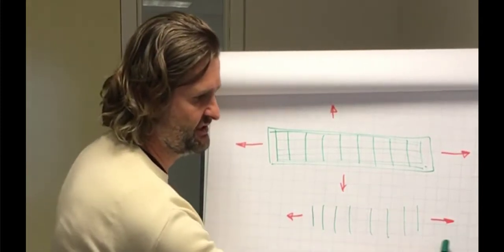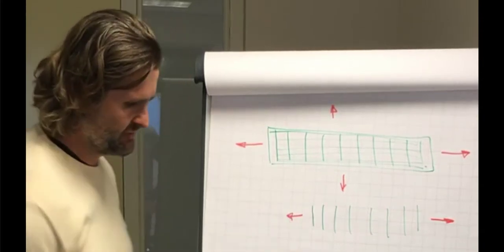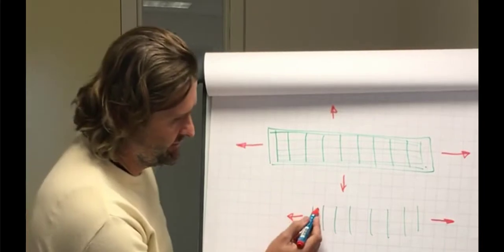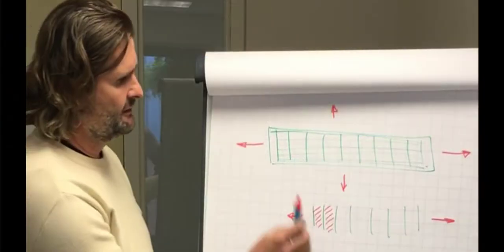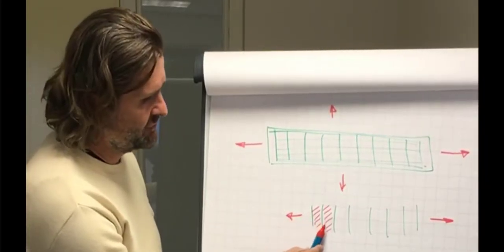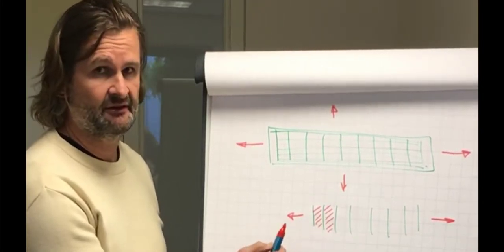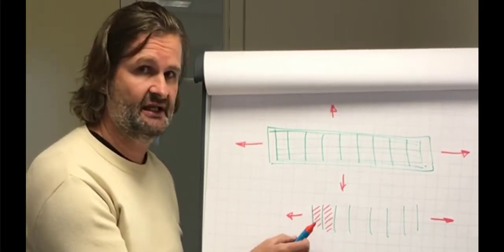They will be stretching in this direction, in the horizontal direction. But there's nothing to keep them together inside this layer, except for a little bit of resin in between the fibers. So basically, the material's elongating, and there's only the resin keeping the fibers together. The fiber itself is not strengthening it in the proper direction in this given layer.